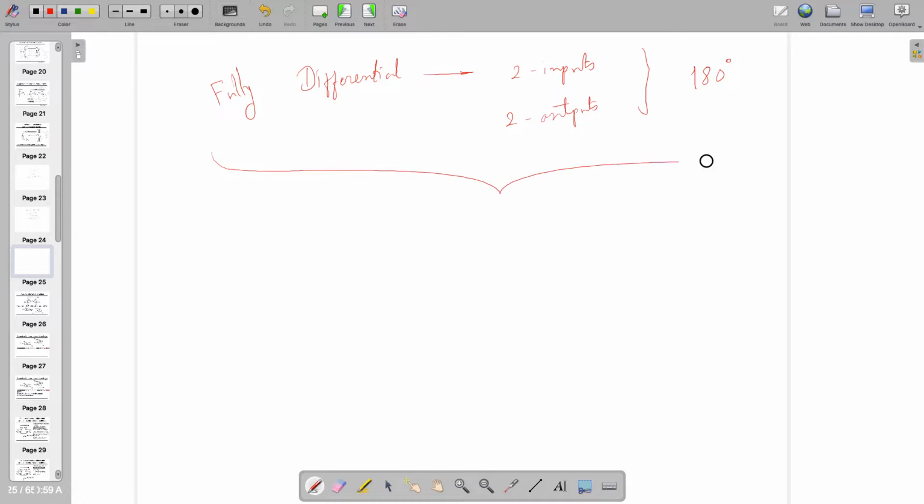This is the thing which we are doing to achieve only one thing, and that's removing second order or even harmonics. Second part is we also want to remove common mode noise. Generally this common mode is DC value, where DC is not purely DC but there are some fluctuations on top of the pure DC. So you want to remove that, and that's what you are doing.